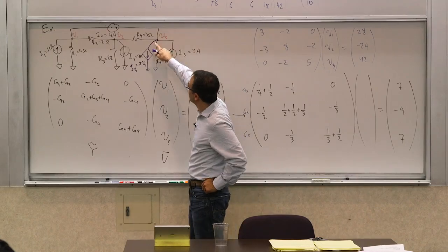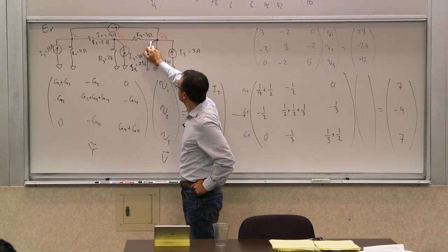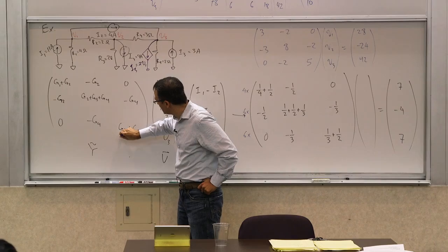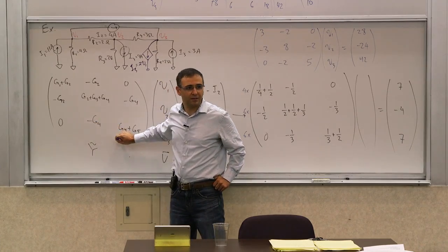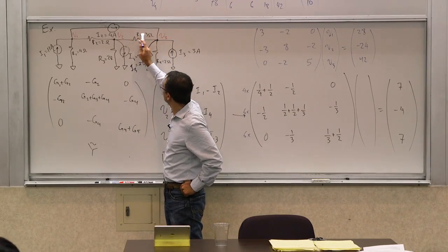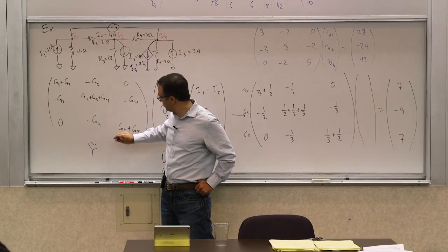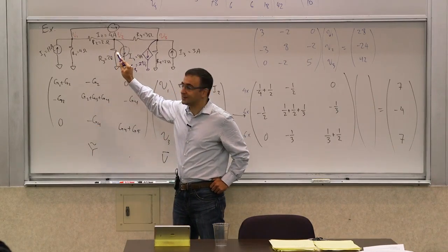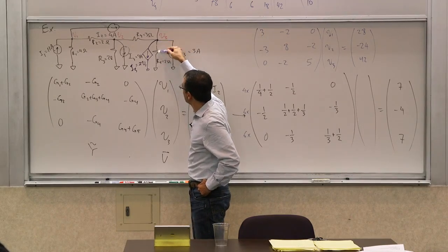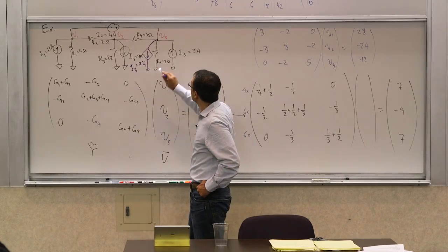The KCL that resulted in this, there were 4 currents before we had this, right? There was the current through this path, which was V2 minus V3, right? Which is reflected by presence of G4 here and there. V2 and V3, right? The current leaving this node really is V3 minus V2 times G4, which basically gives you a positive 1 here and negative 1 here. So these two came from this current. Now, what came from this current, the current through this resistor R5? G5.